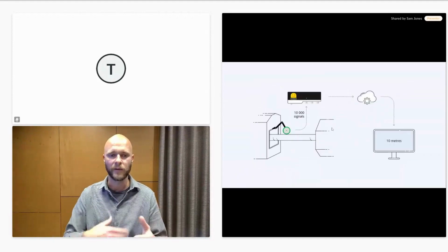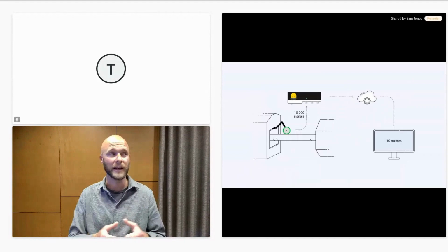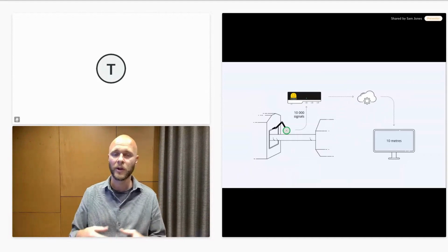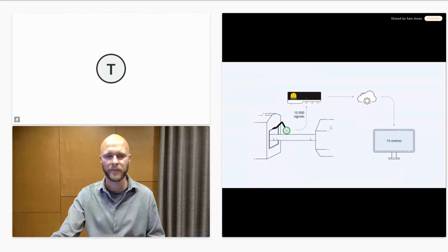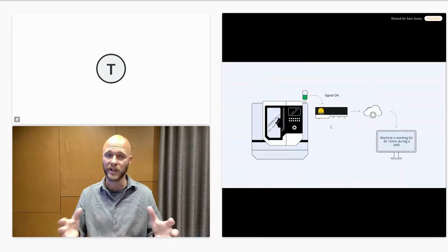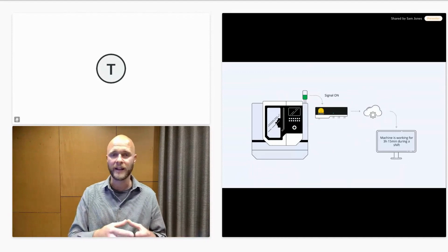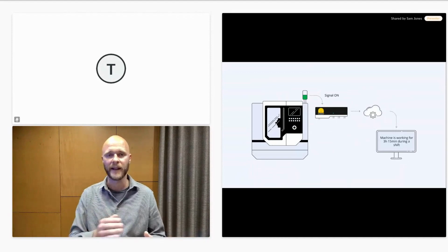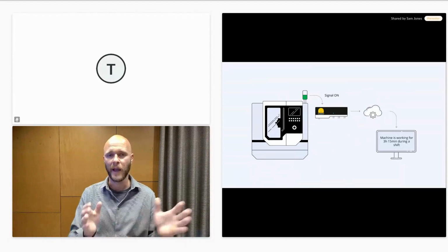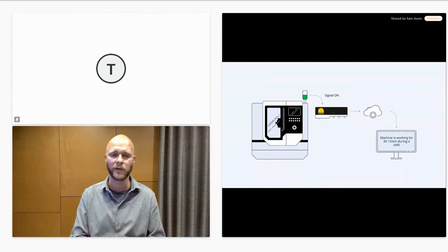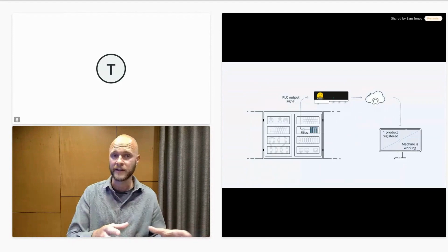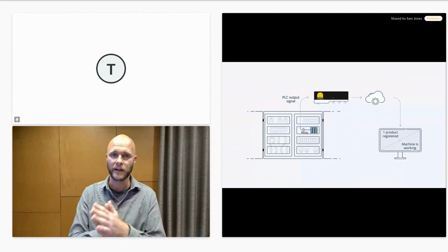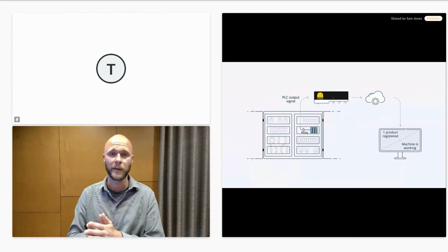Another one would be, if you have continuous production, whether that's an extruder or if you're a sawmill, you can fit, for example, an encoder wheel and measure the length of the product coming out. Another option, if you're a machine shop and you have a lot of CNC machines, instead of actually counting production signals, we can set Evocon to be registering time, what we call time mode. And there we'd be monitoring just the uptime and downtime of the machine. We can also fit a relay kit to the machinery and pick up a signal from the PLC.